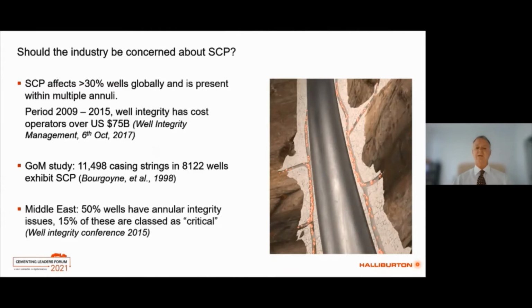Okay, so what should you do next? The well can be killed and secured immediately, or a risk evaluation can be performed and the well allowed to operate for a limited period of time under close surveillance until the barrier integrity has been restored. The main challenge here is how to identify this window in which it is safe to keep production from the well flowing. The answer to this question varies from place to place as legislation, operators' standards, and environmental conditions all play a role in this matter.